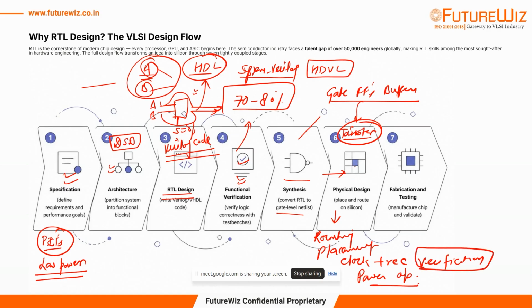In that, the complete PD, which component is going to be placed where, is going to be verified. And then furthermore, if it is functionally correct and physically correct, it will be sent to the fabrication team where the chip is going to be manufactured. And then the silicon that we have in hand is tested again. And if it is bug free, it is sent to the team that assembles it into devices, and we people are enjoying that technology, right?